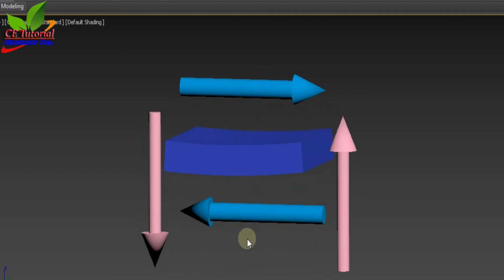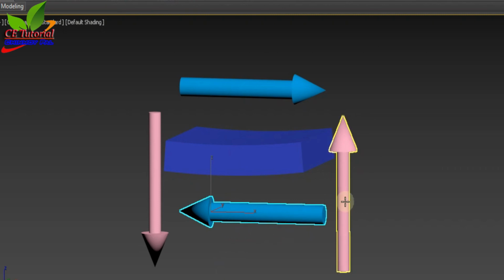Please keep in mind that when we calculate the shear stress and draw the shear stress diagram for a particular section, we are actually calculating the horizontal shear stress, depending upon the distance of this layer from the neutral axis. As we know that both are the same in magnitude, we can say this is also the vertical shear stress.